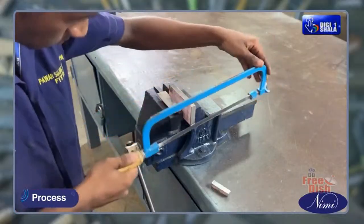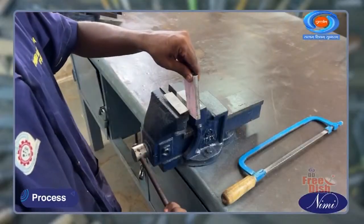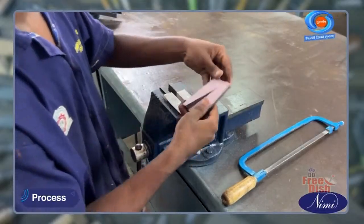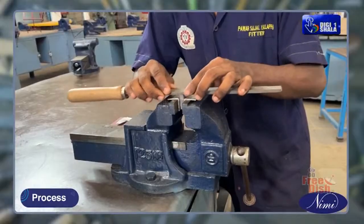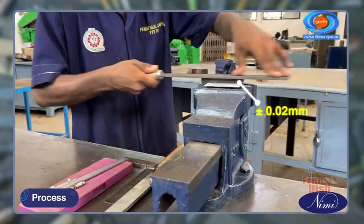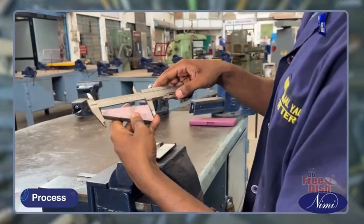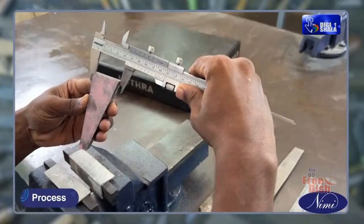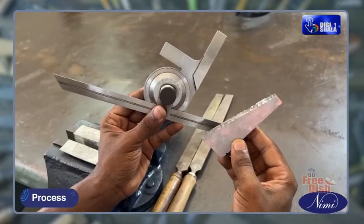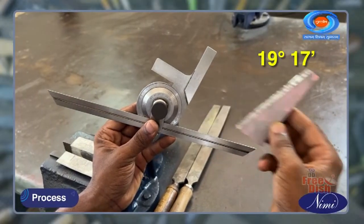Cut off the material into two pieces, part 1 and part 2, by hacksawing as shown in figure 1. File part 1 to size and shape, maintaining the dimensional accuracy plus or minus 0.02 millimeters. Check the dimensions with vernier caliper. Check the angle 19 degrees 17 minutes with vernier bevel protractor.